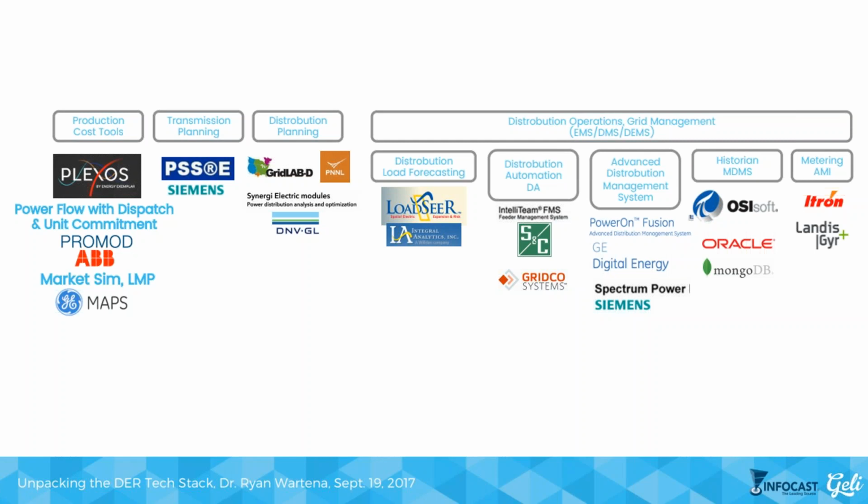But a lot of companies are starting to step in to bridge that, and we'll start opening that up in a moment. We do have traditional distribution automation. These are things like the cap banks, where you can change different set points per the power flow modeling. Then we get a little more dynamic, right? So we get companies like Gridco Systems coming in and putting in variable buck boost converters around distribution networks for more active management of these systems.